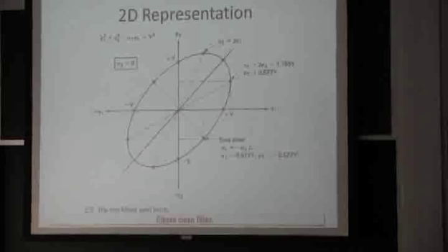And if we apply a tension, if we go back to uniaxial tension from a tensile test, we'll be right here, and we'll still start yielding at Y, the yield stress. But we can see now the effect of applying a different type of loading.